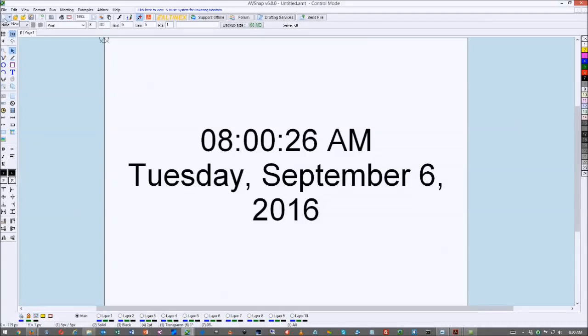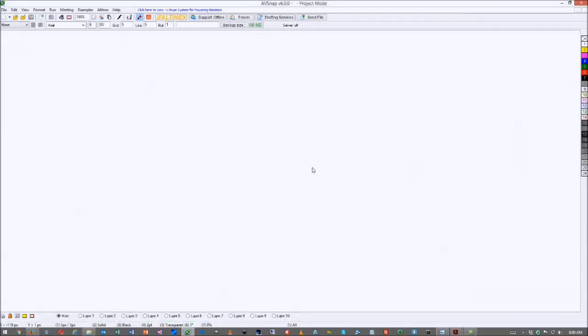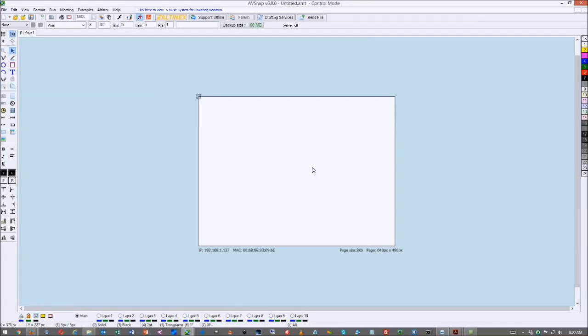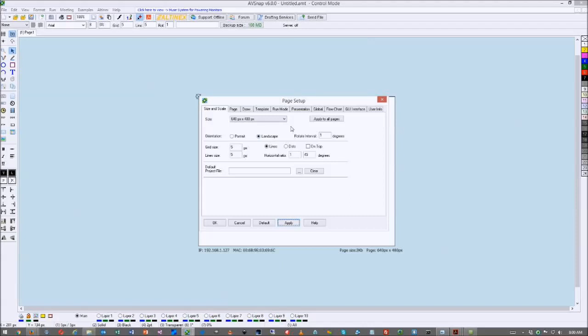Today we're going to cover some library creations, and we had many questions on how to design rack elevations, how to set up libraries for specific applications. So that's exactly what we're going to do. I'm going to start with the rack elevation symbol design and see how we can expand it to different designs. So let's go ahead and start with the page size 22 by 17.